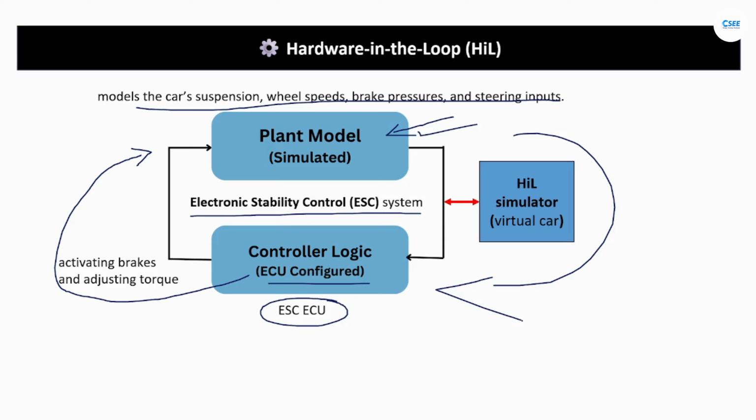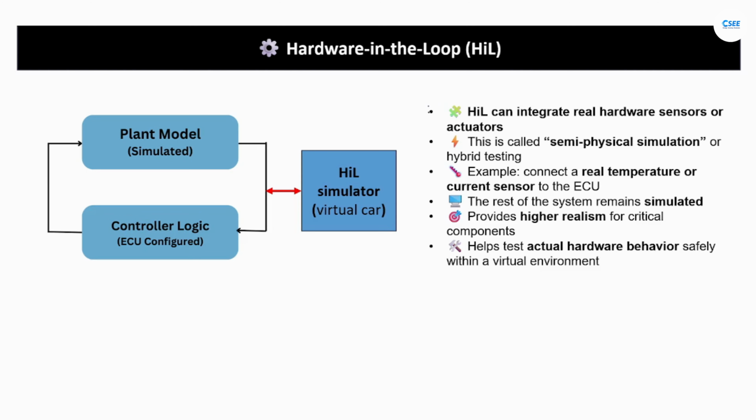HiL setups can also integrate real hardware sensors or actuators. This hybrid testing is sometimes called semi-physical simulation. For example, you can use a real temperature sensor or current sensor connected to the ECU while keeping the rest of the system simulated. This gives even higher realism for critical components.